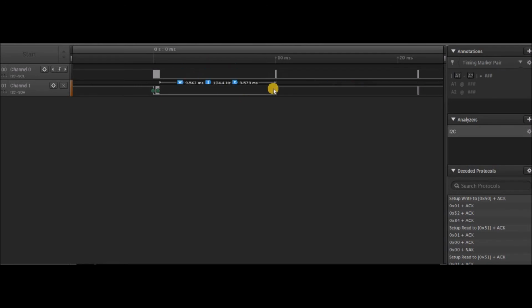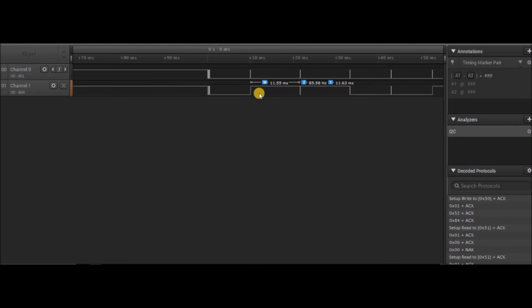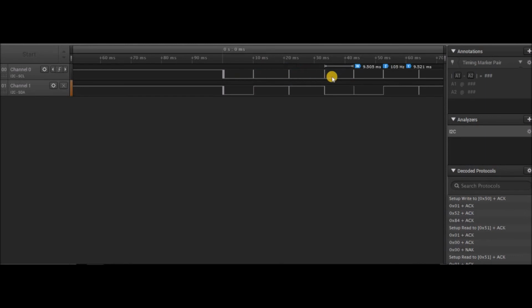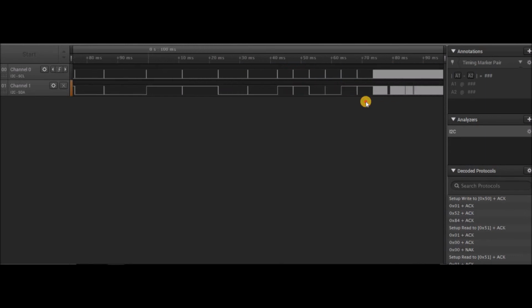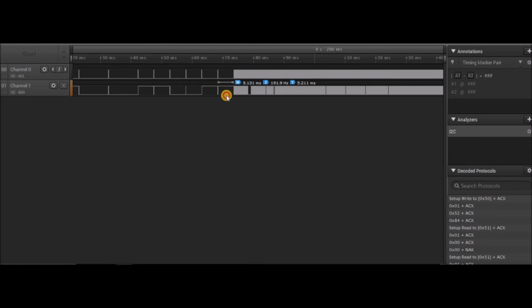The slave then continues by deleting as many sectors as are necessary to delete the complete application space, and we see here that this repeats, so it's deleting 1, 2, 3, 4, 5, 17, 18, 19 sectors in fact, which is true because I know that it's deleting 19 kilobytes, and one sector on the KL02 happens to be 1 kilobyte in size. So now we turn our attention to what happens when we start programming.